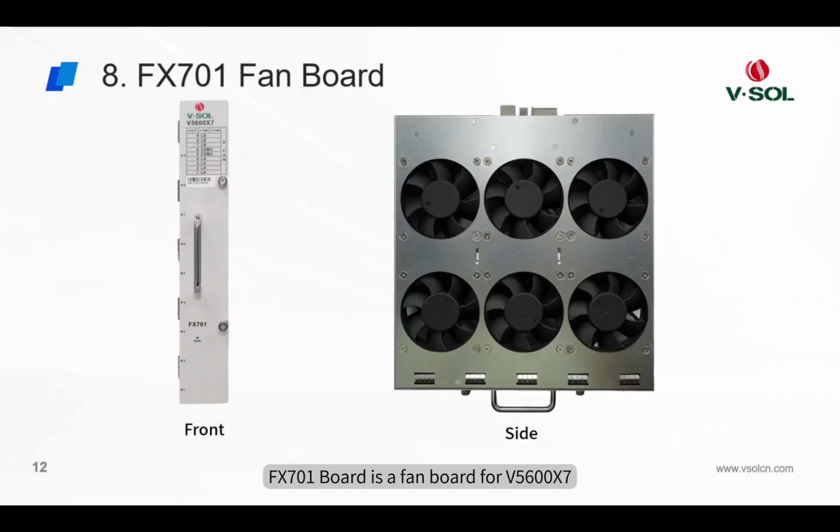FX701 board is a fan board for V5600X7. From its side view, it can be seen that it has 6 high-speed fans, each of which can be controlled separately, and supports adaptive temperature adjustment of wind speed, ensuring good heat dissipation effect of the chassis OLT. The available slot to connect fan board is slot 0.